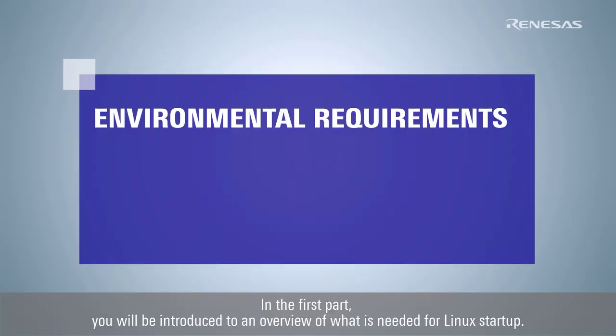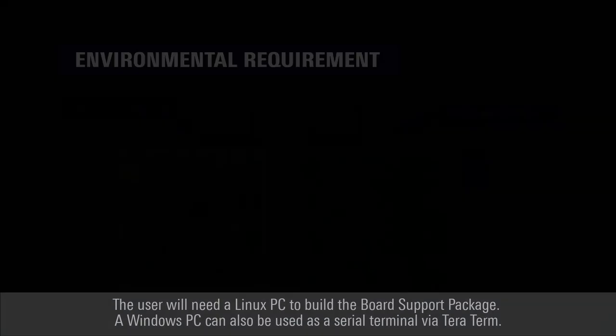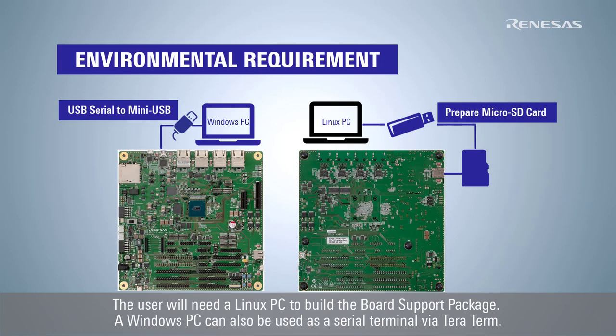In the first part, you will be introduced to an overview of what is needed for Linux startup. The user will need a Linux PC to build the board support package. A Windows PC can also be used as a serial terminal via Tera Term.